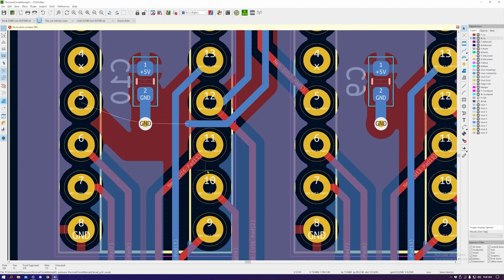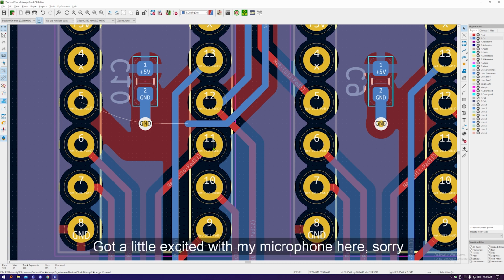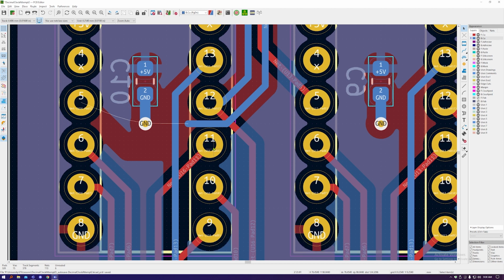So what a via does is, these yellow circles are mounting holes that the pins or legs of the through-hole components are going to go through, and they're plated through holes, which means they connect to the front and the back, and you put your pin through it, put a load of solder on, that holds your component there. So what we can do is basically make a small version of those to just send a signal from front to back. We're not putting anything through it, but it's still plated, which means there's copper in between the two layers, so it creates a direct connection between the two layers electrically.